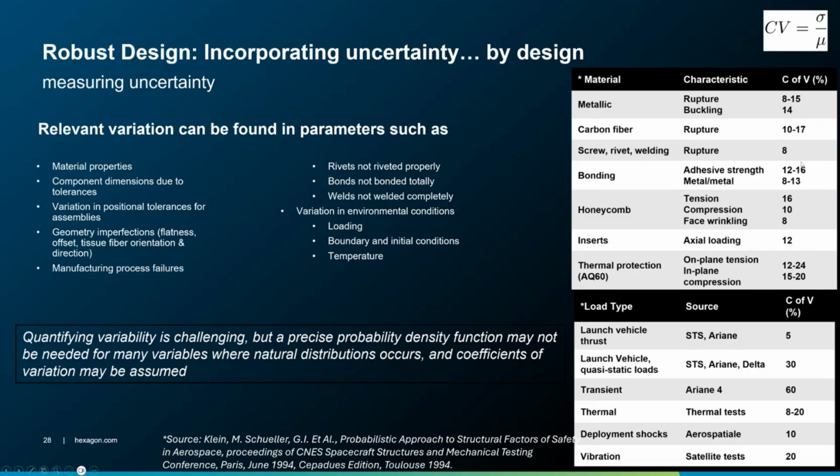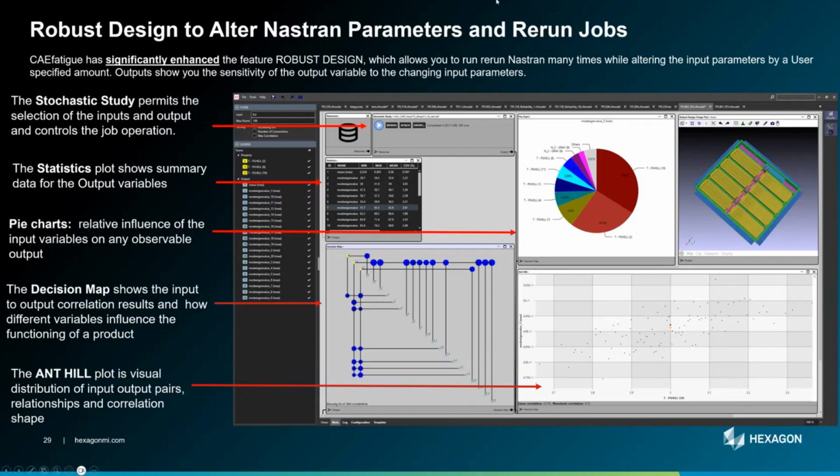And you can see here, if you scroll a bit the numbers, it's never really below 5%, right? Never. Sometimes it's dramatically high. But what I'm trying to say here is that if you just make an initial conservative assumption that you can always go back and correct, that you have a 5% flat uncertainty everywhere, you're not far from the truth. Okay, and this means that quantifying this variability is useful, but it's not necessary to take benefit and to start enhancing your design with the robustness investigation.